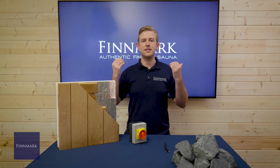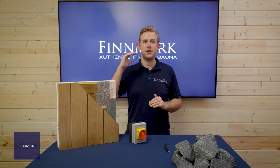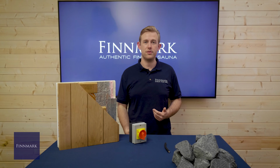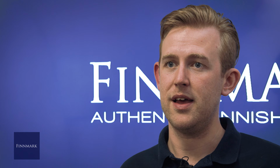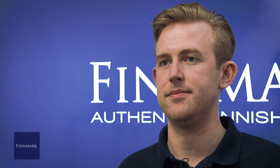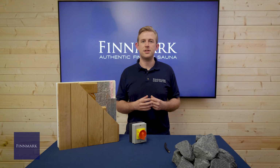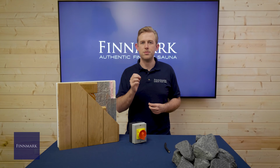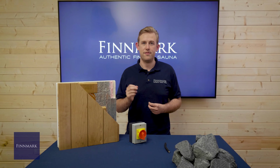This helps bring the heat and humidity fully down over the users and helps to prevent stratification of heat, which makes the user's head feel really hot and their feet feel really cold. The ventilation extraction should be aluminium or galvanized steel. This is because of the heat and humidity of the air extracted from a sauna. The ventilation setup will differ from project to project, but a good sauna designer will be able to work with you and an M&E contractor to model the optimum airflow setup and ensure that it is Legionnaire's disease safe.